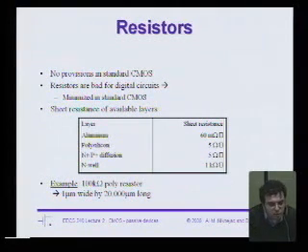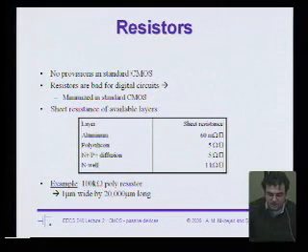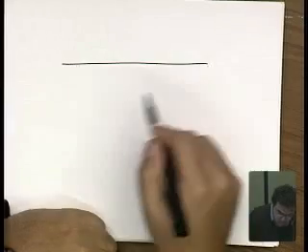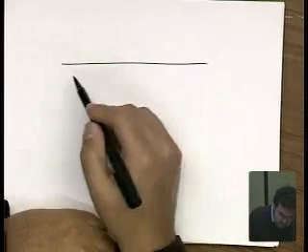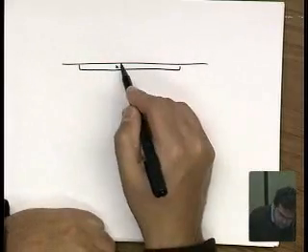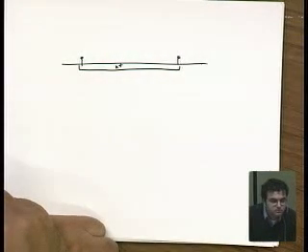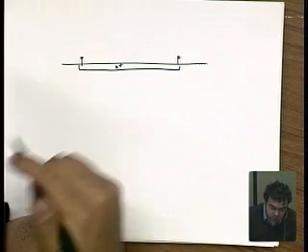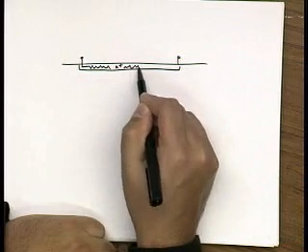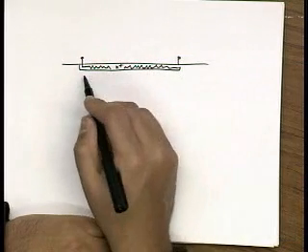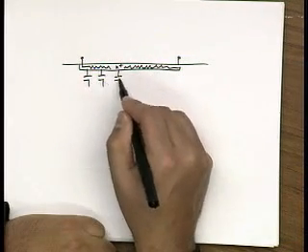Temperature variability. Okay, temperature. What would you worry about probably more than temperature? All right, let's look at what a diffusion resistor looks like. Let's say I just make an N plus region and I put contacts on either side. Is this a resistor? Yeah, it's going to be a resistor. But it's also a distributed nonlinear capacitor, right?